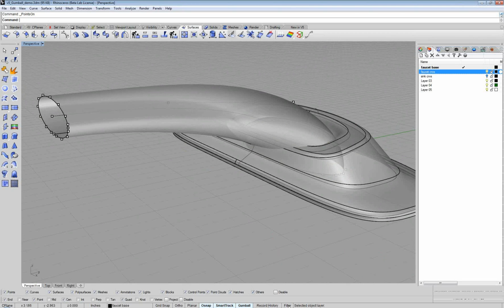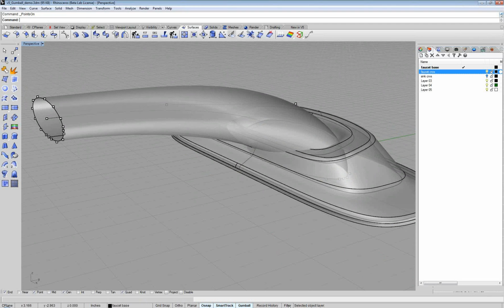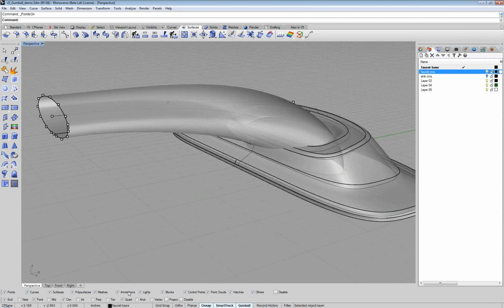So also at the bottom of the screen you'll see the word Filter. Filter will hide and show, as you left-click on it, a series of checkboxes that looks kind of like the object snap checkboxes. These are selection filters. So if I want to only select control points, I could left-click on these other boxes and manually deselect them. But I can also right-click over the checkbox for control points. And if I right-click over that checkbox, that's the only one selected. So now I can't select anything but control points. And this is another method for isolating your selection versus locking objects or putting them on locked layers. So it's selection filters, and you can hide and display those boxes with the Filter word at the very bottom of the interface.